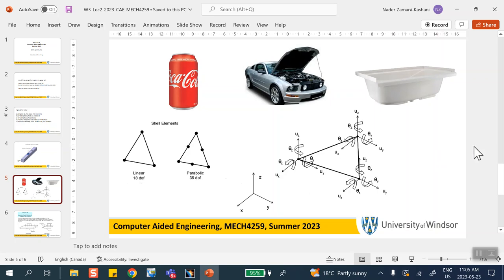In real life, those stresses are not zero, may be very small. So shell theory obviously is not as accurate as the solid elements, and one reason is this assumption. So if the thickness direction is x, the normal stress in the x direction and the shears, sigma x, tau xy, tau xz are zero.